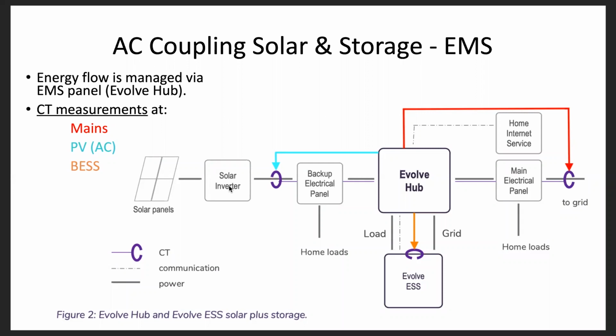So say the sequence of events is when the grid goes down, that connection is lost and there's a 4-second delay before the battery comes online as a voltage source. Those backup loads are then served after that 4-second outage. All the lights and everything come back on. That solar inverter that's connected to that backup loads panel will see that new voltage source as its synchronizing voltage.